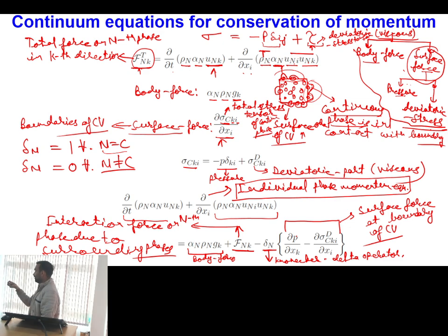So these two features make pressure a scalar quantity. That is the reason there is no subscript with the pressure. So in all the directions, whether you calculate pressure on a control volume in x direction, y direction, z direction, everywhere it will have the same magnitude.